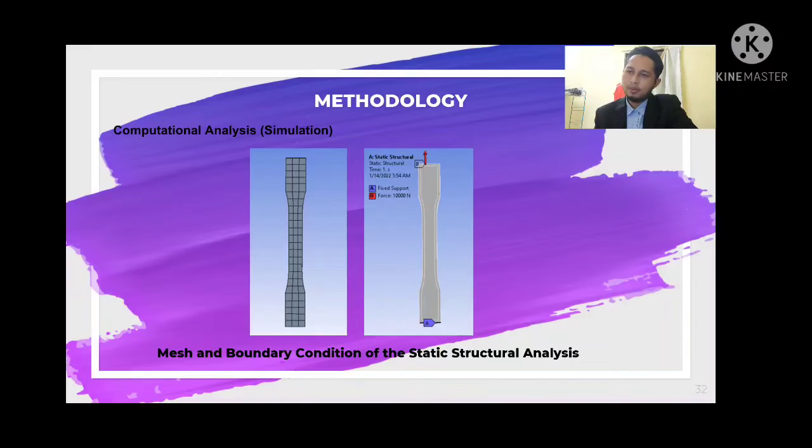Convert the CAD file to IGS file and import the 3D models to ANSYS Workbench. Apply engineering data of PLA to the specimens. Select Auto Mesh for suitable mesh size on different models. Apply fixed support on one end of the specimen. Apply a vector force of 10 kN in the direction of the y-axis.